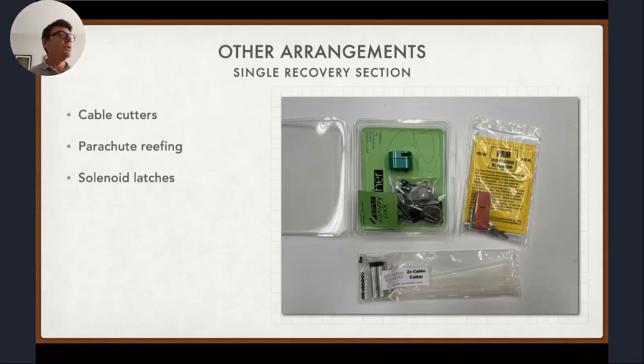So what people have done is use surgical tubing and made a sealed charge. You can use black powder that way. You just have to be very careful. What I tend to do when I'm flying higher, though, is I move away from black powder and I go to CO2 systems. I personally like the system that Tom Rouse used to make, the CD3 system, but there's also one that's sold by Fruity Chutes that I just haven't used yet. So you can seal black powder charges to work above 40,000 feet, but generally it's probably about the time where you'd switch over to CO2.